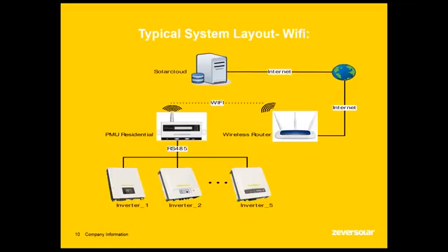The ZeverCom may also come with a power pack. However, the unit will derive its power from the RS485, so there's no need to connect this. The ZeverCom unit, once connected, will emit a network signal, which you'll need to connect to the customer's Wi-Fi network, which we'll go into more detail shortly. The internet will then connect to the Solar Cloud, which will update the information on the customer's Solar Cloud account.